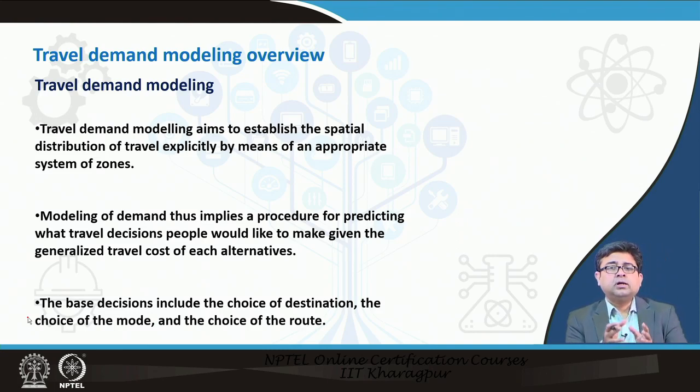If you know the predominantly residential land uses and the predominantly commercial or office land uses, you could predict with a certain degree of accuracy that the traffic will flow from the residences to the office buildings, and similarly in the evening it will be the opposite traffic flow. So, at a macro level your prediction is accurate.